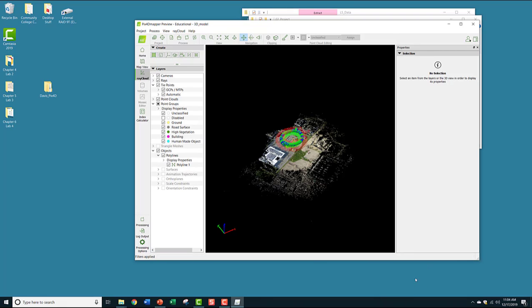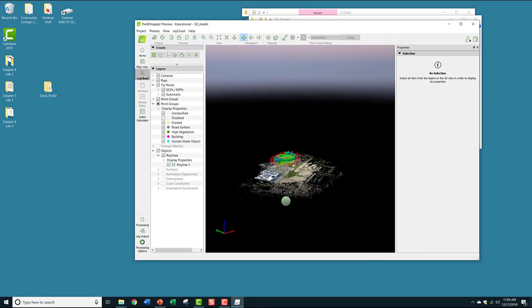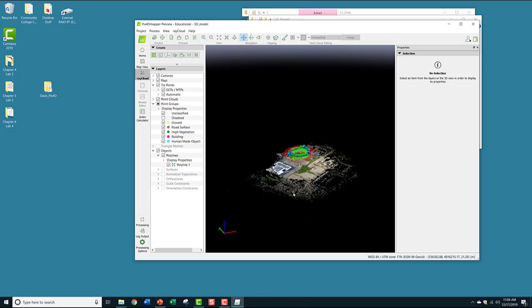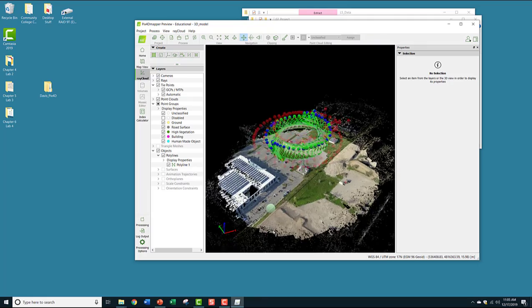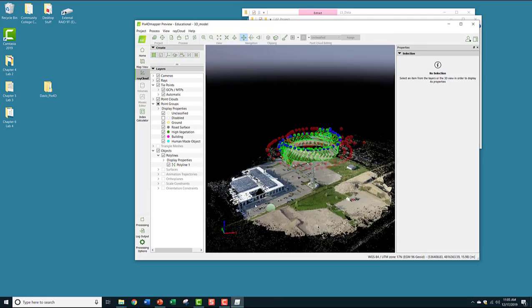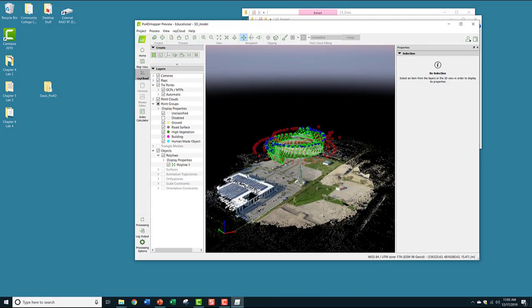Then use the navigation tools to explore this area. Take a few minutes and explore it, go in and out, and see how your cameras are rotating around it. Also notice that the angles of the photos are oblique instead of nadir, or straight down. Notice that the extents of the DPC spread out far beyond the tower itself.